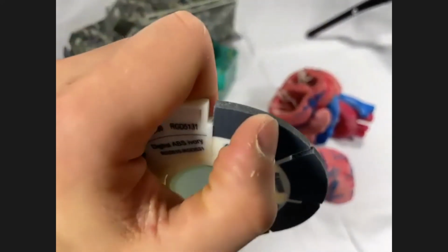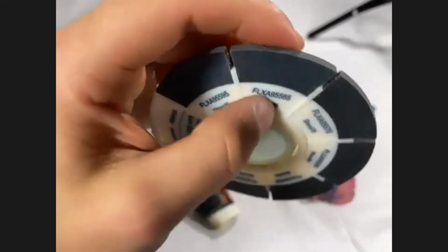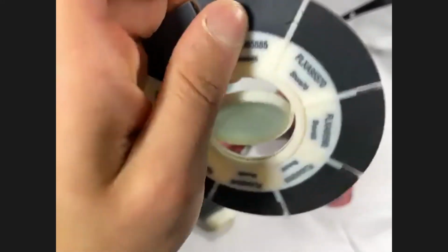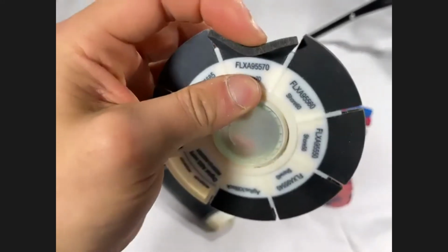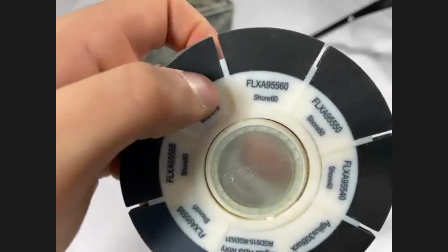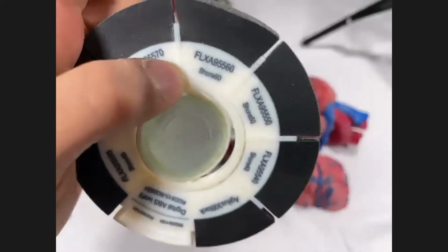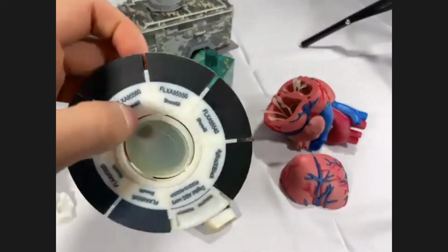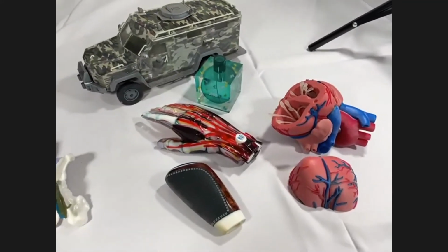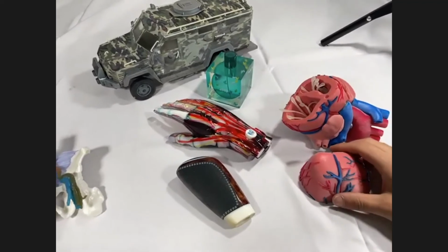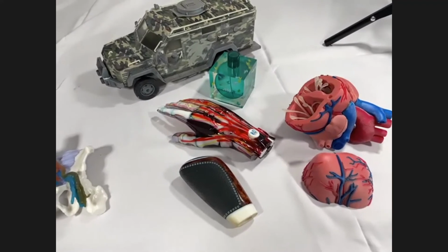But if you're doing a coating on the handle, you can do different grip simulation based on assigning different properties. So if you do split it up so that you have different bodies that you can apply those different shore values to, you can change it. There is no way to do a gradient where it's one body and you start at like 30 at one side and 95 at the other. But yeah, if you have the body, you can select one shore value at a time. And depending on the thickness, it may feel a little bit different, but it's still a certain shore value that you selected.